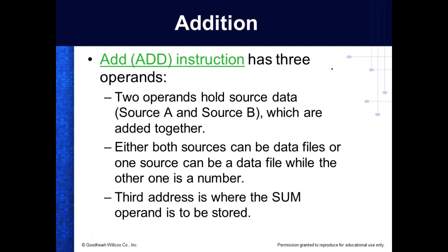Yeah, and where we're getting it from, we can get it from our F8. You can get it from the input. If you can address your inputs, you could get it from your input port. You'd say I:0, right? And you'd pull that right out of the input data file, and you could add it, and then you could turn around and store it in the output. So the results of your math operation, you could store it in a 16-bit output port.